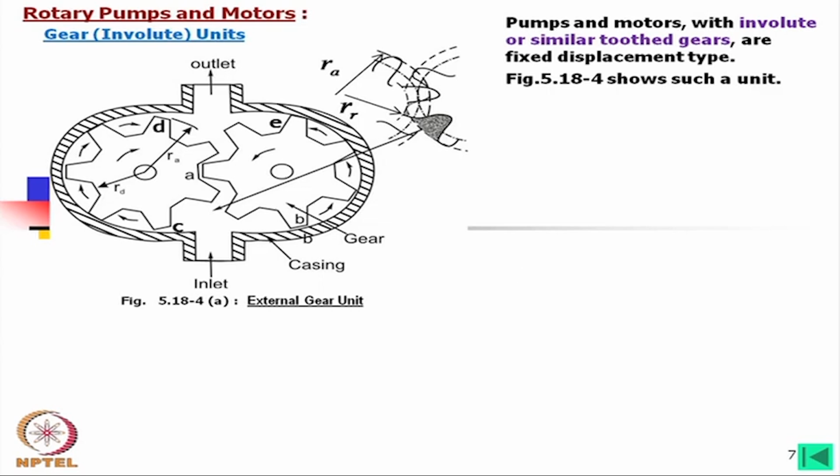Now, for gear pump, we can use corrected gears, and even go for 10 number of teeth or below. For a 30-degree pressure angle, for 10 teeth not much correction is required, but for 20-degree there corrections are required. So, with those corrections, and also sometimes the tips are truncated or made longer, there will be slight change from the pure or ideal involute profile.